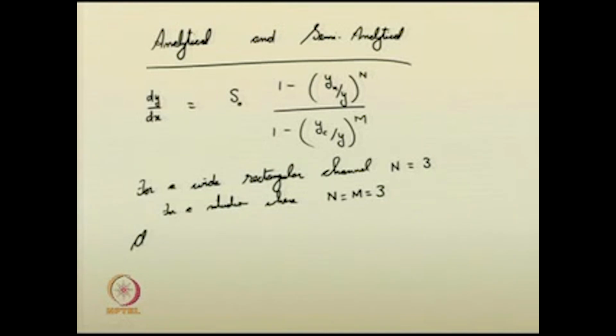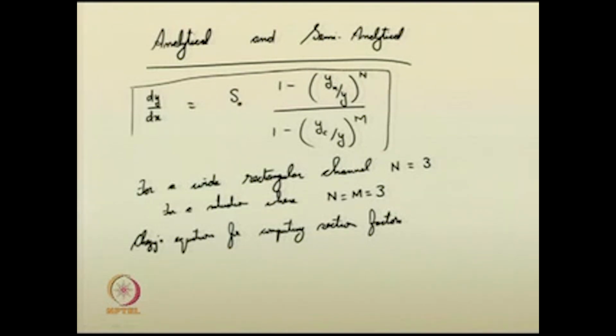Chezy's equation for computing section factors, instead of Manning's equation, if you have used Chezy's equation for computing section factors in critical flow and all, then you will observe that this particular dynamic equation can be solved with the following expression.